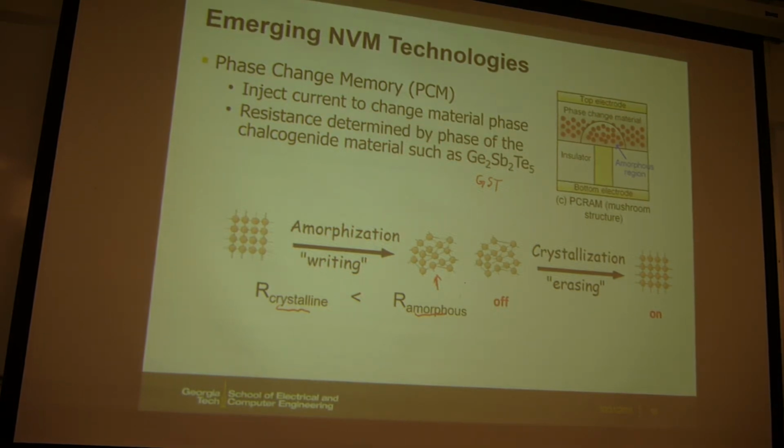Okay. Since this has already been used in 3D XPoint, does 3D XPoint have higher energy consumption than 3D NAND? Yes or no. So at the cell level, yes. As I just said, you need to apply heat. But of course, in the circuit, you don't have heat to apply. So what you do is pass current. Use Joule heating, right? Current, I squared R. You have the Joule heat. So you need to pass much current. So in that sense, the write power is high.